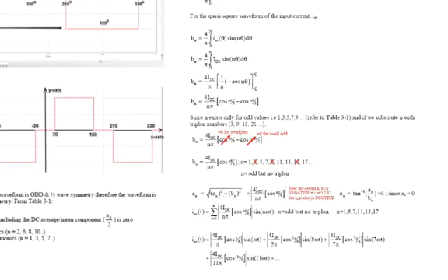Therefore, we put in the absolute value, which is 4 IDC over n pi cos n pi over 6, because we have to be careful that for certain values of n, for example 5, 7, 17, it will become a negative value, but we know that Cn is always positive because of the modulus, the absolute value. So for the angle, it's always An over Bn, and An is 0, so the angle is 0.